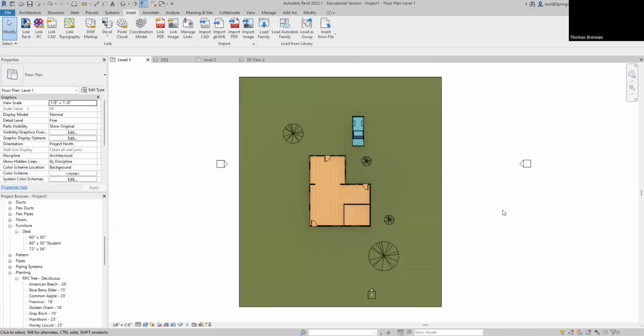Is there a way we can drag the building off? Probably best to drag the ground. If the ground's not where you want it, just delete it and put new ground in. If you try to do it in 3D, that might be why it's not working right. You want to put your ground in at level one. Level one is how it's supposed to work.